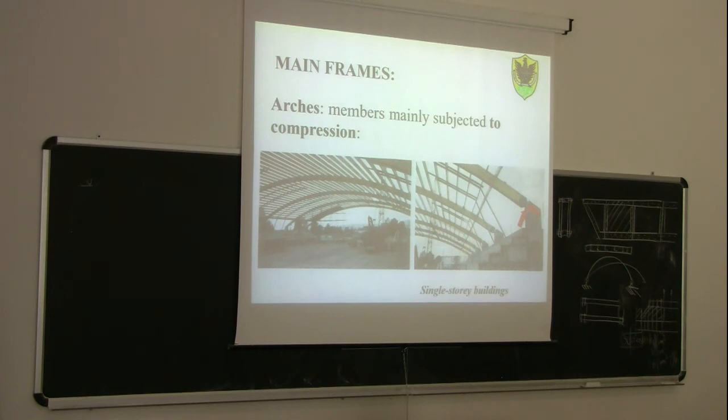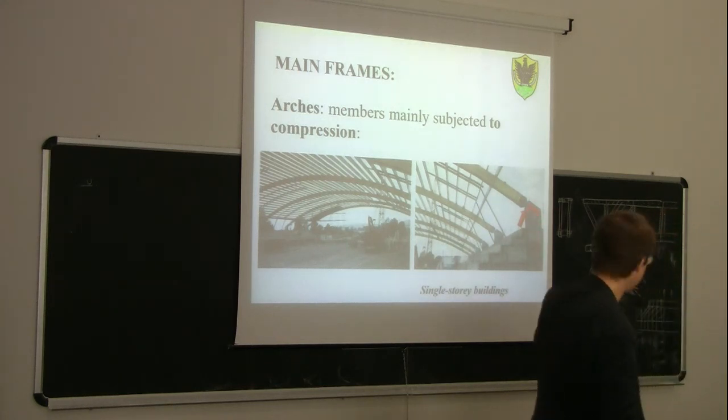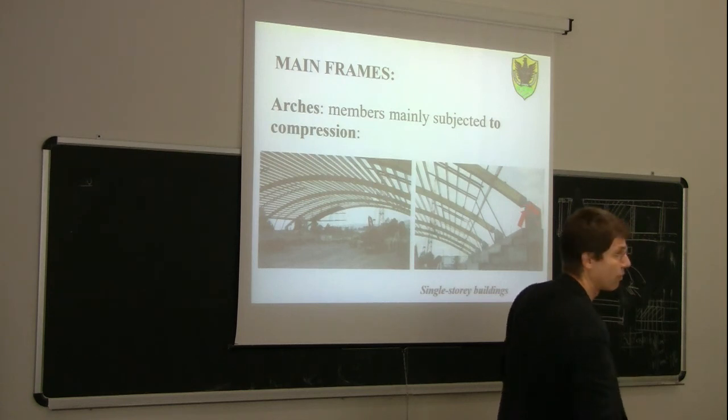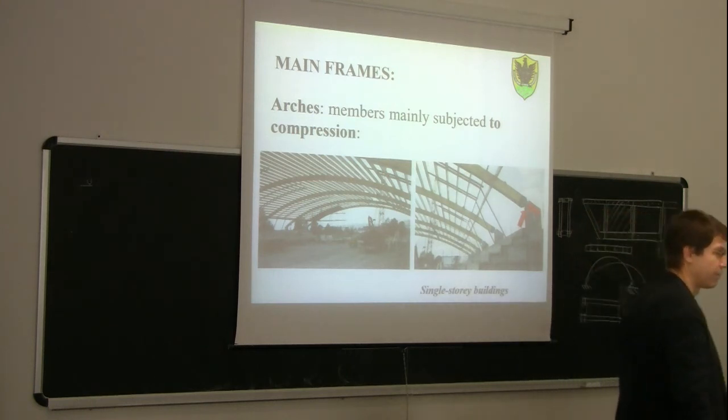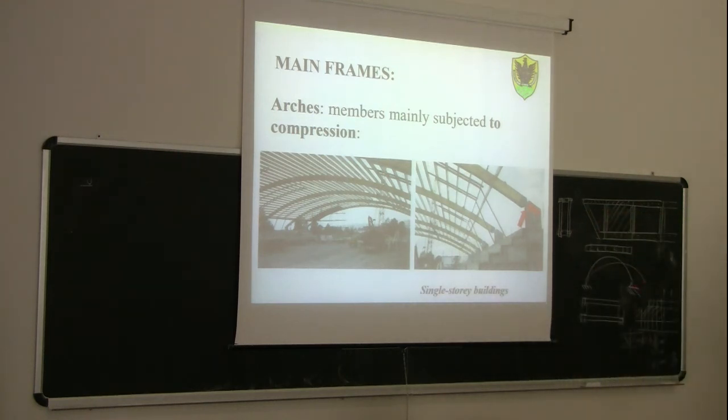Okay? For this reason, you can see here, this squat cantilever was made of reinforced concrete to make sure that this deflection here is very small. Because if they had done this out of timber, the horizontal deflection would have been 3 times, and then we would have a behavior not very good as an arch, more as a curve. Okay?